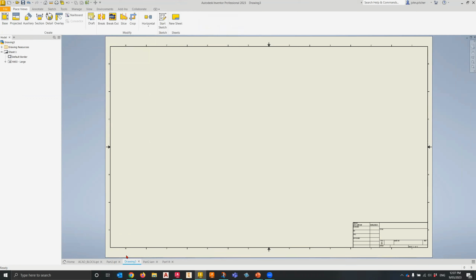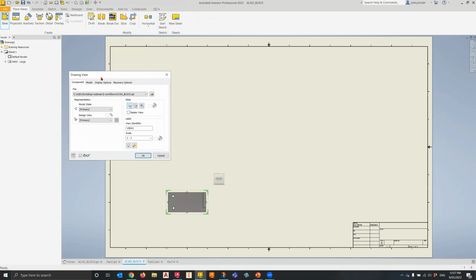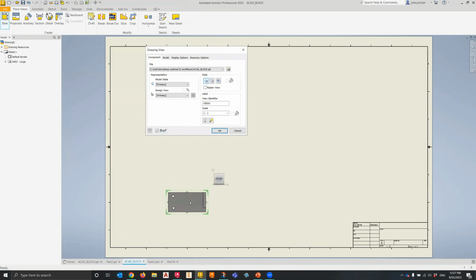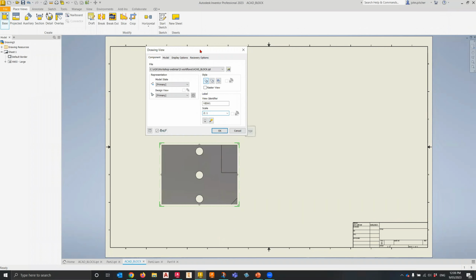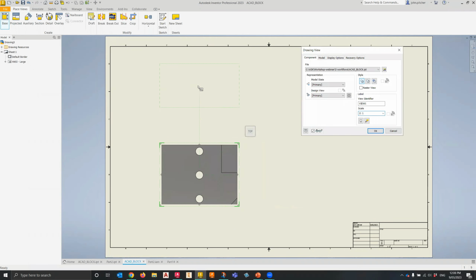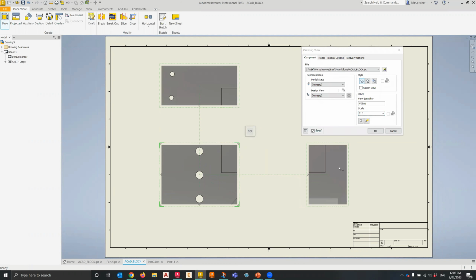So a standard drawing in Inventor looks a bit like this. Basically, when we create a model of a particular part, we can simply pick up here to see which particular views we might like to have on our drawing sheet. Obviously, we can change our scale up here and make this a little larger. But effectively, within this situation, we can very quickly create our isometric views and work with the different areas and elements of this.